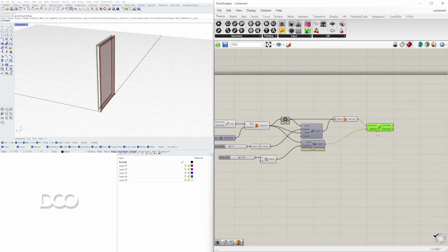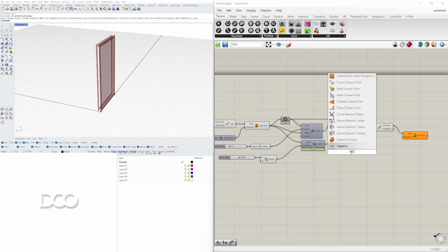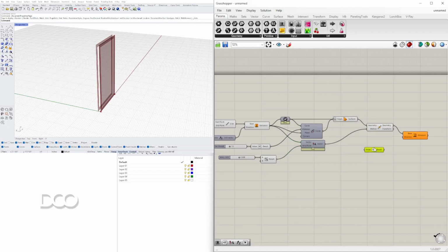Then, once this is moved, that same surface is extruded in the opposite direction, so negative, and by twice that amount. So go to times 2, which will give me a multiplication of 2.